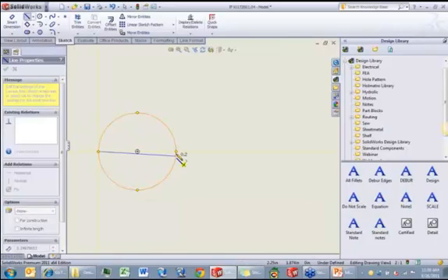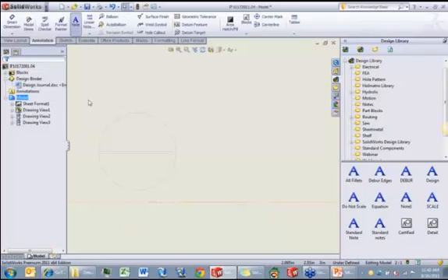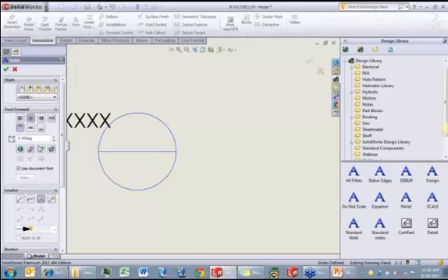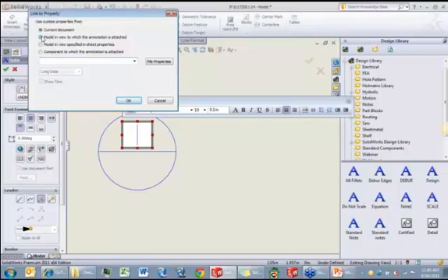Okay, we'll add some more sketch entities here. This is going to be a detail block. And I'll just put in some various notes in here. Let's see, we'll turn off the leader, center justification. I want this to be my detail number, so I'm going to go ahead and use the link to property option and link it to the view that the block is going to be attached to. Okay.